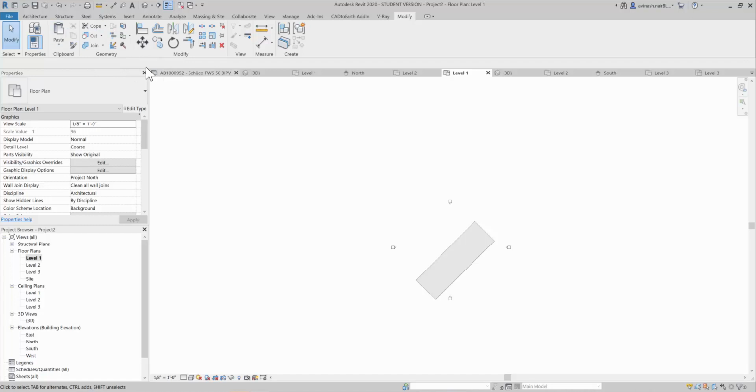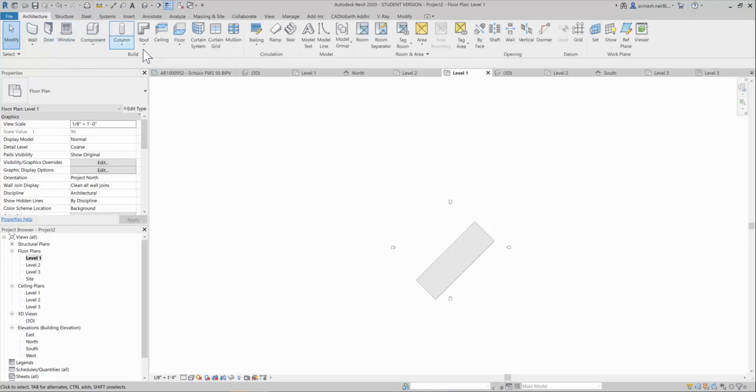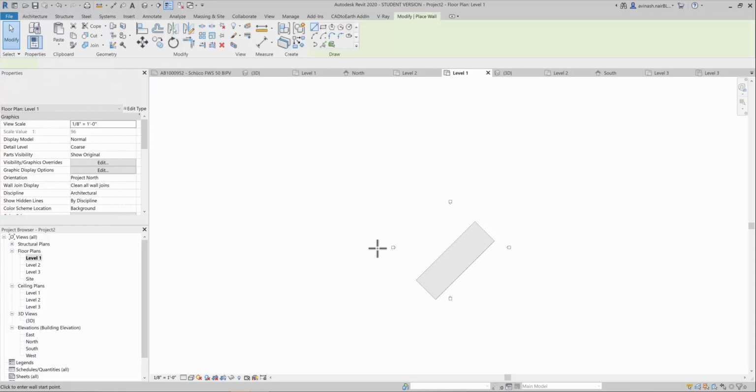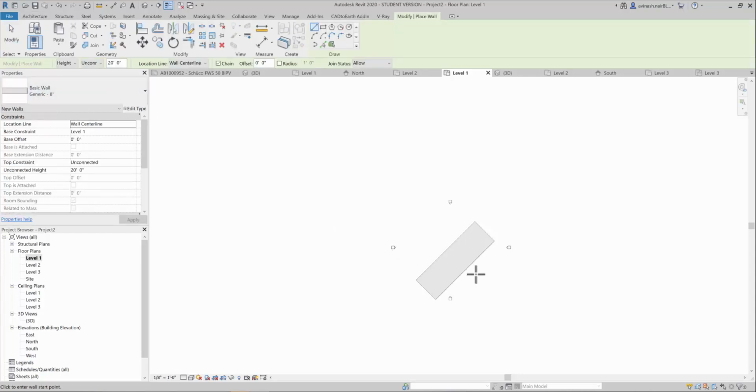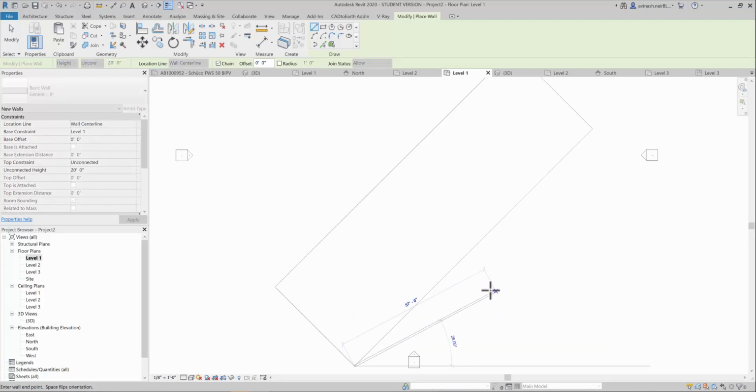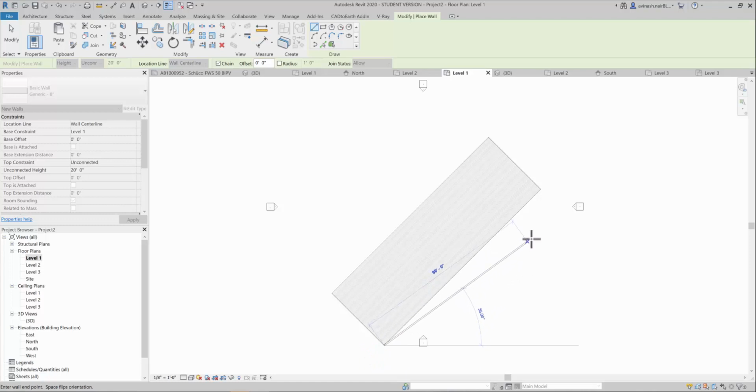the facade here. To make a facade, what you have to do is first create a wall. I selected the architectural wall here, and you have to go to facade wall. You always need to go in an anti-clockwise manner. Only if you go in anti-clockwise manner, you will get your mullions inside and the cover cap outside.